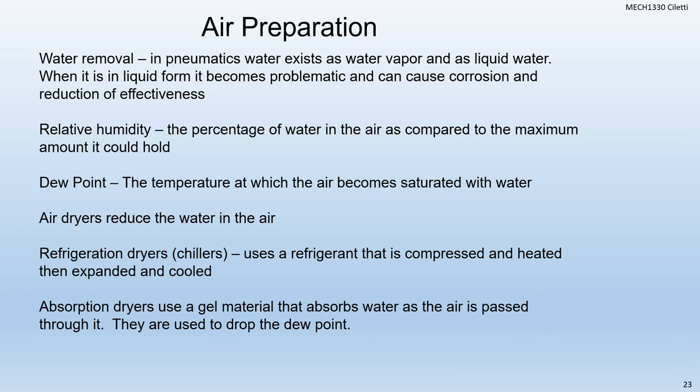In pneumatics, water exists as water vapor and as liquid water. When it is in liquid form, it becomes problematic because it can cause corrosion and reduction of effectiveness. That corrosion with air produces rust, and chips on the inside get those particles inside. So we always pay attention to what the relative humidity is.